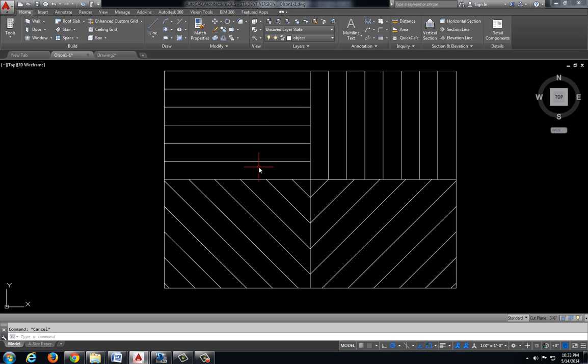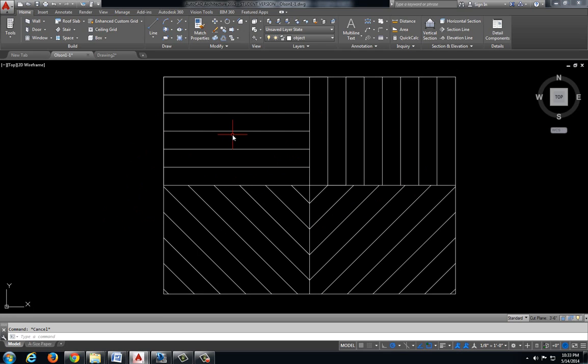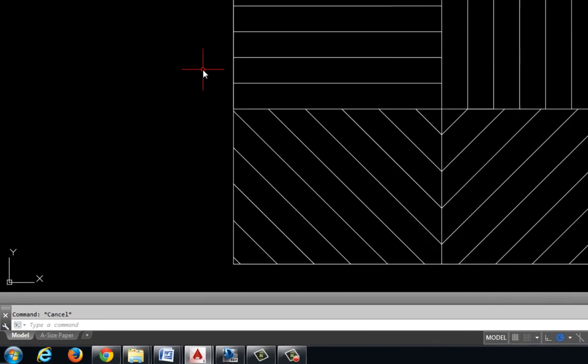So we have our drawing area. This is called model space. Anything when we're just kind of free drawing, when we open up our template, that is model space. In AutoCAD, there's kind of 2 different worlds, if you will. There's model space and there's paper space.